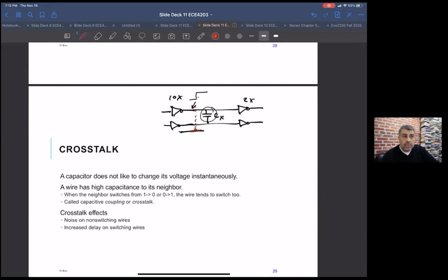It might increase the power consumption a while because that glitch gets settled by the current through this guy. This guy will have to provide the current to settle that glitch. So that's an additional current that'll have to pump in. And it increases the delay that just even this guy has, because it's also driving this capacitance. So there are consequences even if you don't completely flip the other line, but depending on these values, you have some level of protection. So let's look at those.